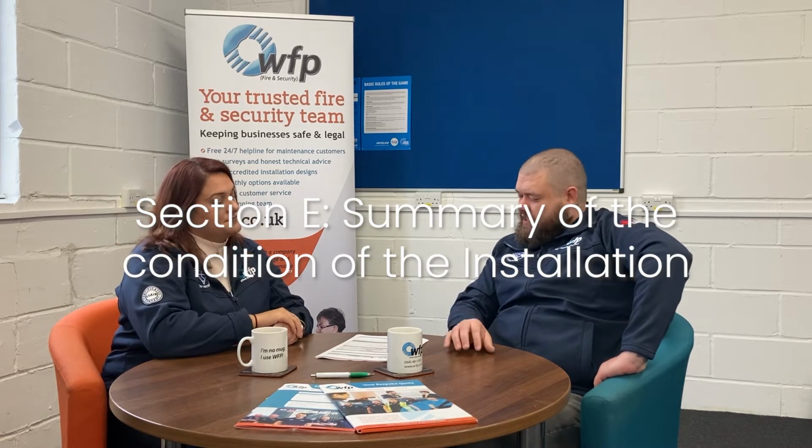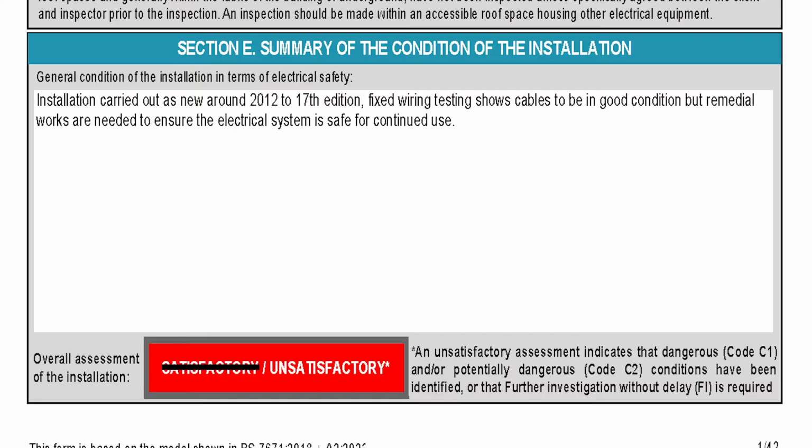Section E is the summary of the condition of the installation. That's a real brief summary. So in this case, we've put installation carried out as new around 2012, 270 condition regulations at the time. Fixed wire tester shows cables to be in good condition, but remedial works are needed to ensure the electrical system is safe for continued use. So we've said the hard wiring, the wires are okay, but actually there are other issues, which as you go into the observations you'd start unveiling. But it's just a real quick summary of the condition.